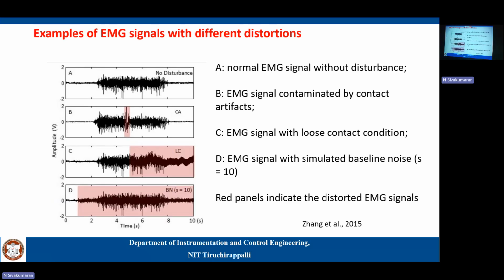This is a very nice paper I found in the literature. Normally this is EMG, just a single burst, as you have seen in the demonstration session. The artifacts will be something like this: for example, some glitches there. Whenever we see something like that, it means there is some noise. This is an unwanted glitch, and this is also some noise. It basically starts somewhere here, so this is also some baseline noise. You cannot see clean activity.